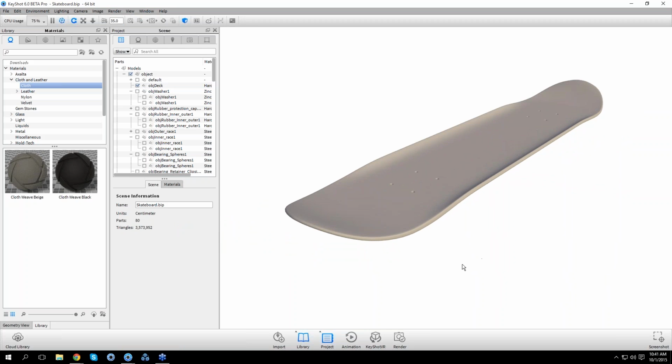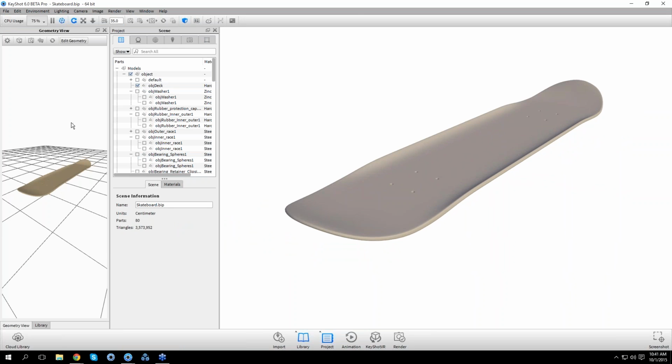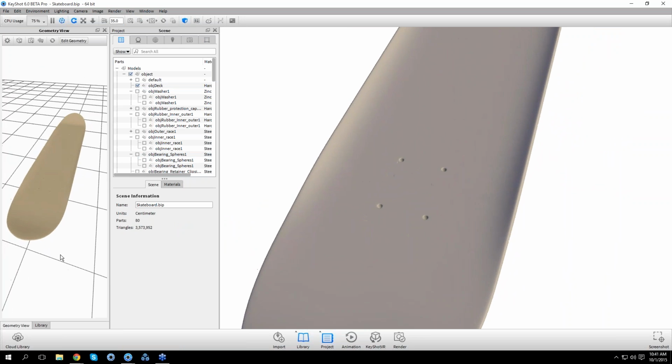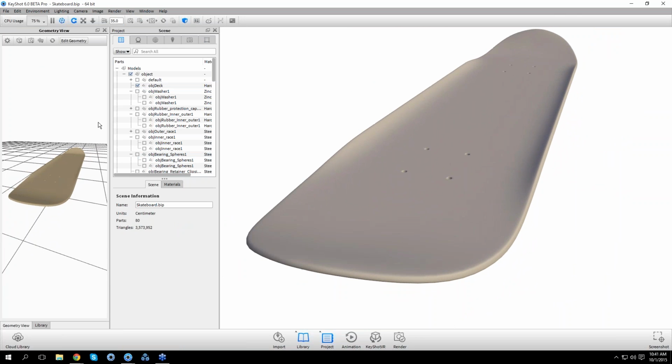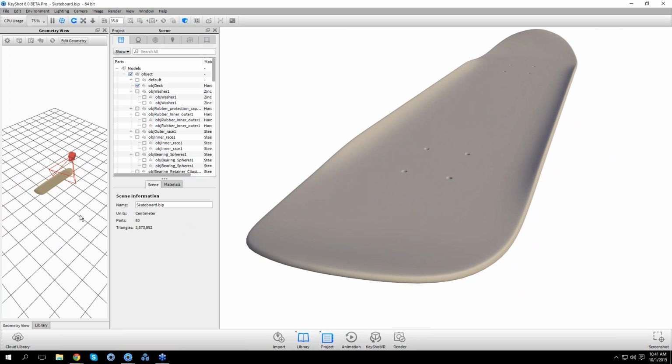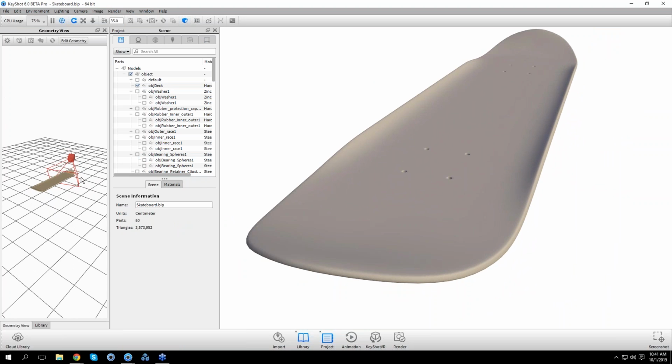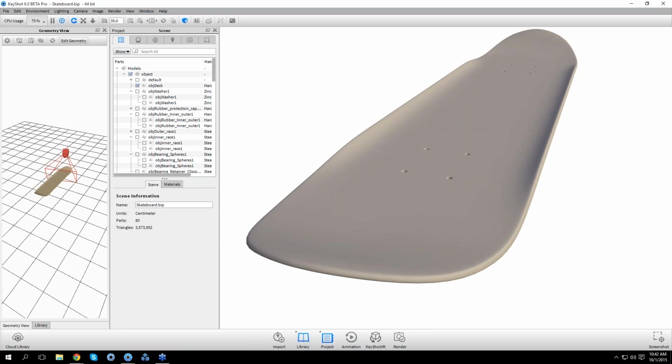And there's an awesome new tool in KeyShot 6 Pro, which is the geometry editor. So I'll just open up my geometry view window. This is also a KeyShot 6 Pro only feature. Here I have a secondary viewport where I can change this to a different camera. In the case of positioning those planes in the glasses scene I just had up, the geometry view is very helpful to move those planes around, move your physical lights around without disrupting your view in the real time.